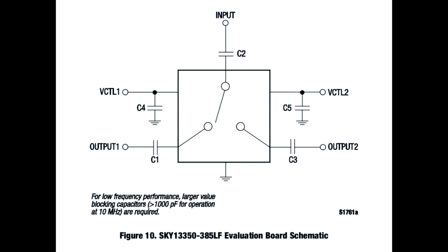Here's another example that uses DC blocking capacitors. This is an RF switch. Remember I mentioned I had a couple of RF switches on YARD Stick One? These components are typically pretty easy to use. Now, they do tend to come in small packages. The ones on HackRF are particularly hateful because they're 1 millimeter by 1 millimeter 6-pin QFNs.